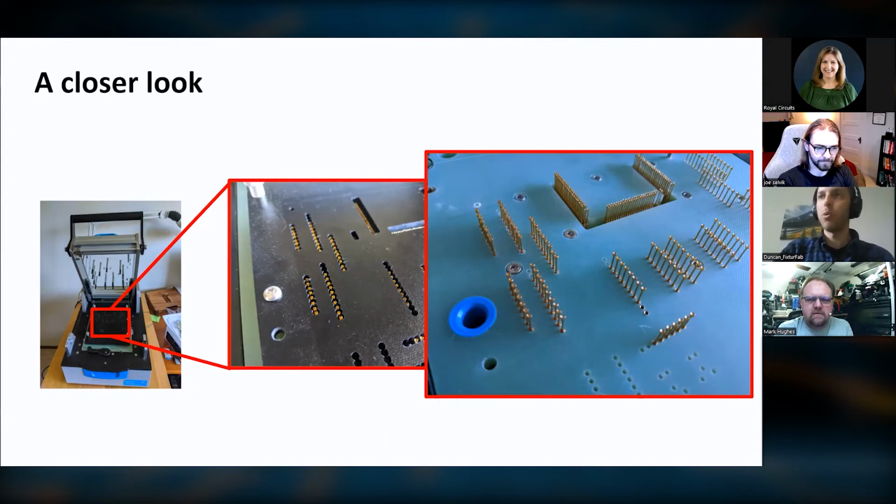Yeah, so a couple ways. One, use a programmable power supply where you can control when power is applied via software. You can have a switch detect when the fixture is actually closed. In the case of this fixture, we have an inductive sensor in there, which detects when the entire frame is closed.